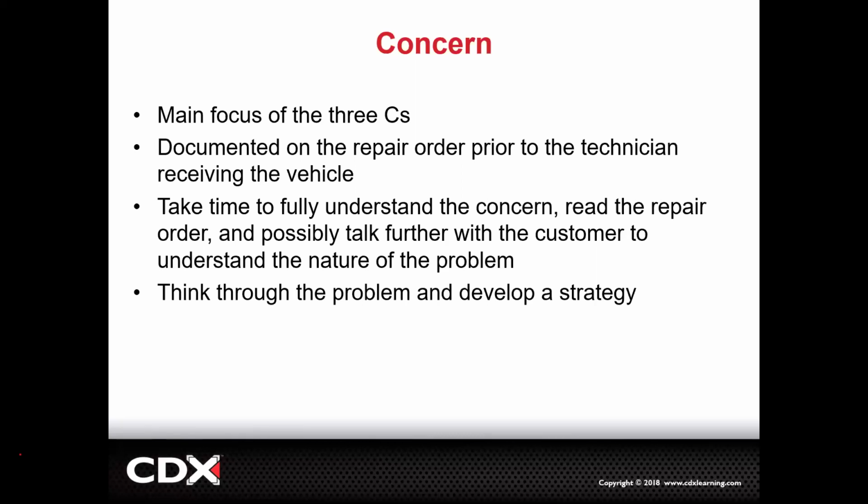Was it a gradual failure? If it was a gradual failure, what do you think my thoughts are? Sounds like a leak to me. Right? If it's a gradual failure, it sounds like a leak to me. If they're saying, oh no, it was cold in the morning and then on the way home it was warm, I'm thinking, maybe not, right? But the customer concern guides the whole process at the beginning.